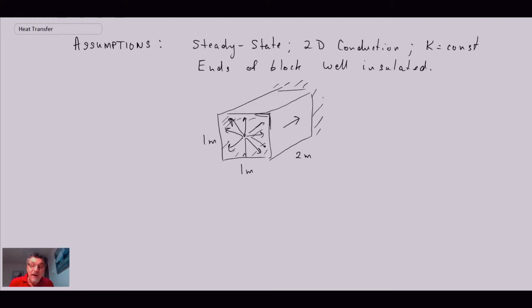Okay, so analysis. How are we going to solve this? We're going to use the shape factor. You have to find a table that has a shape factor with this object in it. That's usually step one for solving these problems. And I just happen to have a table that has this value in it. So we look up the conduction shape factor.